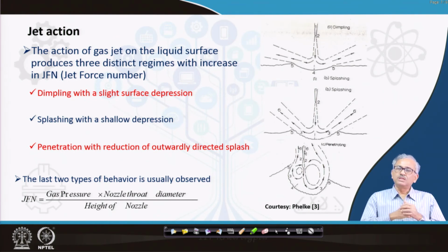Okay, and in that case, the rate of decarburization may be higher than the rate of formation of FeO. So in that case, what happens sometimes is that the slag becomes very dry, because it is the FeO that basically contributes to forming the low melting eutectics. So if you have a significant amount of FeO, the slag fluidity really increases, because it forms a lot of low temperature eutectics. So if FeO decreases in the slag, then it becomes viscous and dry. That is called the drying of slag, and that is not good at all, because if the slag is viscous or dried, then the mass transfer in the slag will be very less. So you cannot effectively transfer the impurities to the slag phase. So that is called the drying.